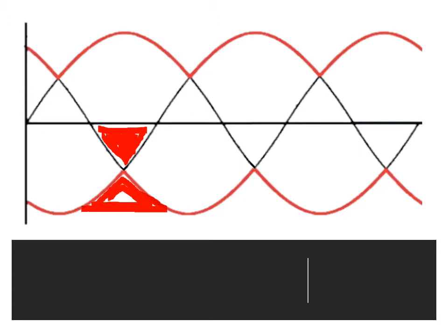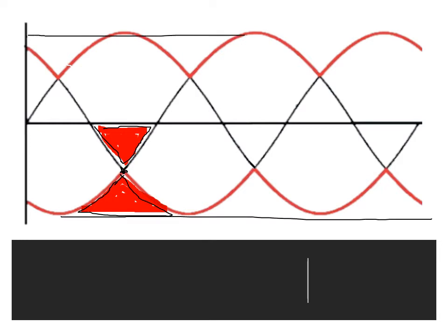And this is one of the major advantages of three-phase, that not only does the voltage never go to 0, as we see going across the top, but even when it is at its lowest point, as in here, the overlap of the two voltages will actually come together to fill in the valley. Filling it in, giving us a constant continuous push in a negative voltage and a constant continuous push in the positive.